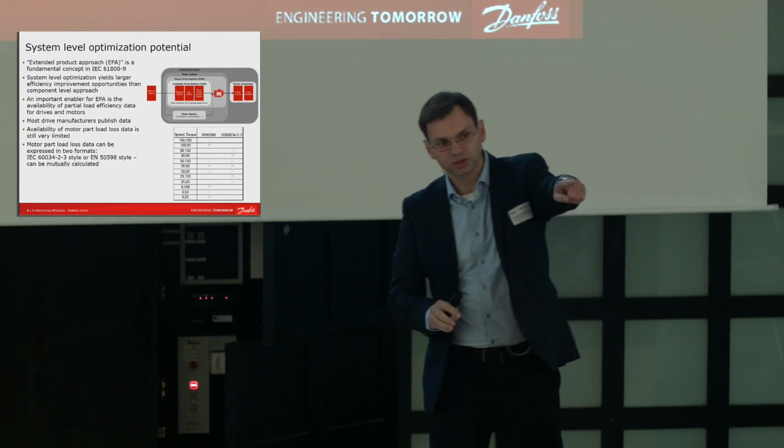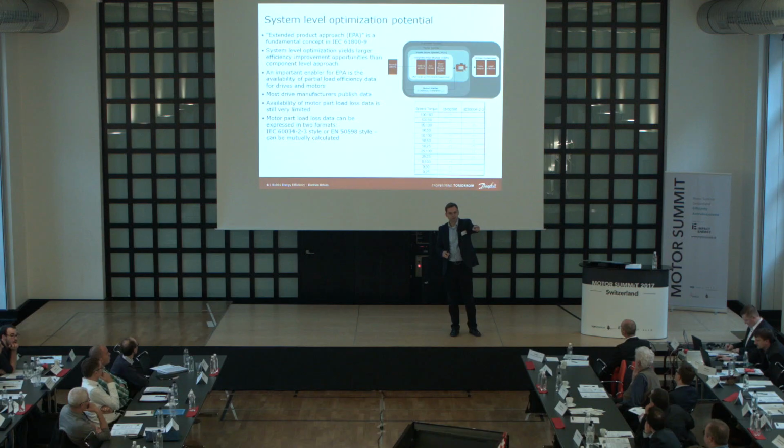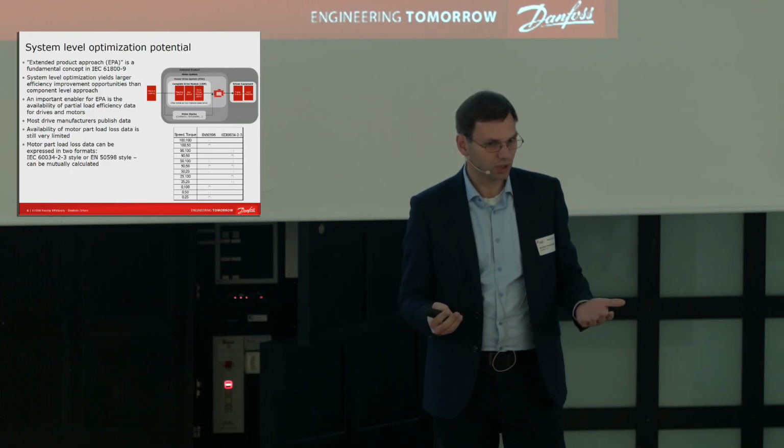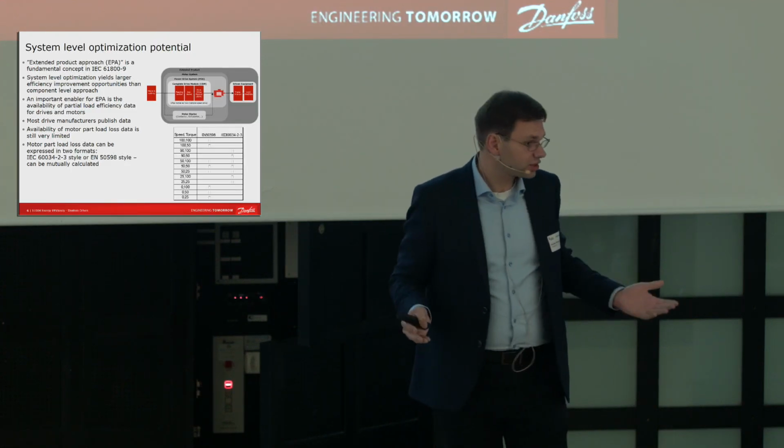You can see that demonstration over there. I hope all of you saw how the efficiency drops in partial load. It's very important to understand what the efficiency of the components is in part load. For drives, it's not a problem.